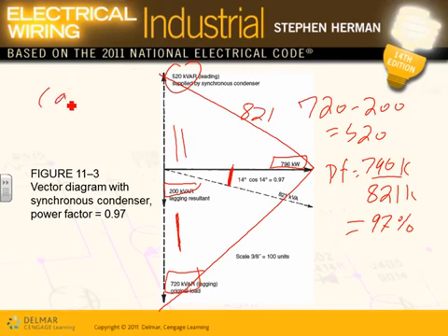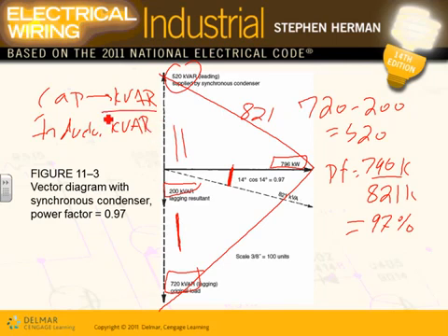If you have a capacitor, the kVAR of the capacitor, and if you have an inductor, the kVAR, these are like black and white. These are opposite of each other, and they neutralize each other. So Karen, if I want to kill 100 kVAR coming out of motors, coils, what do you do? You add 100 kVAR of capacitors. Did you guys hear me? Do you understand this concept? By adding kVARs of capacitors to kill the kVARs of motors.